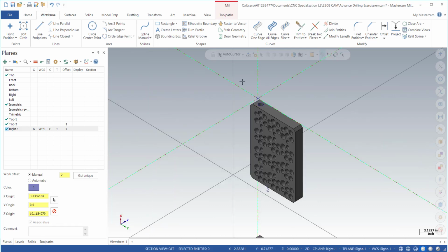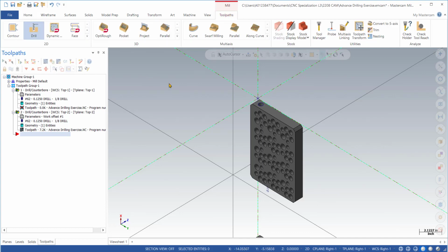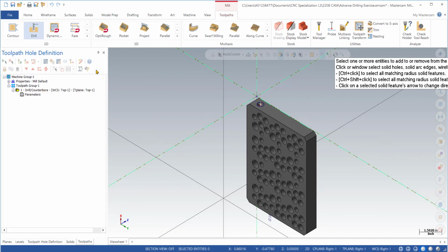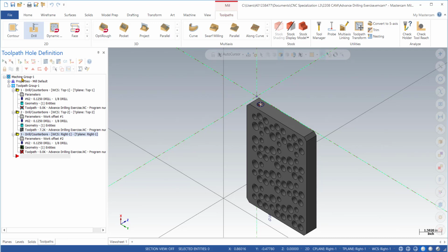go to isometric, and then one more time I'm going to go to toolpath, and we would create another drill toolpath. In drill, I would just pick the center, and I would just say okay to everything else because we have all the parameters in there already, right?